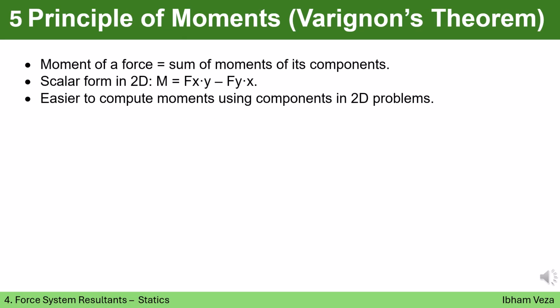Principle of moments. Varignon's theorem. Varignon's theorem states that the moment of a force is equal to the sum of the moments of its components. Instead of working with the original force, we can resolve it into horizontal and vertical components and calculate their moments separately. This often simplifies calculations significantly.